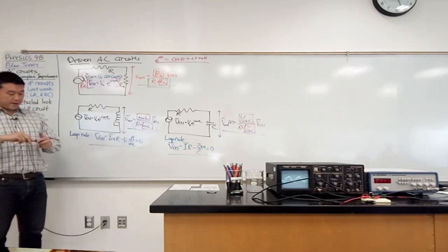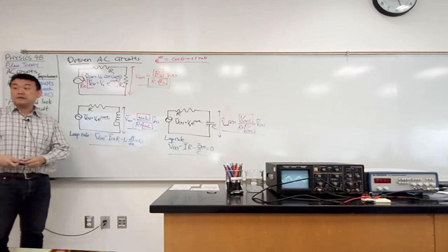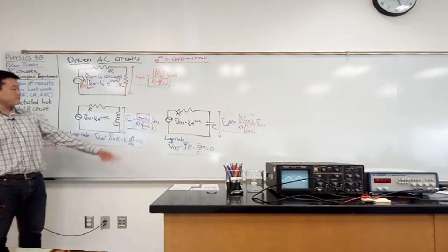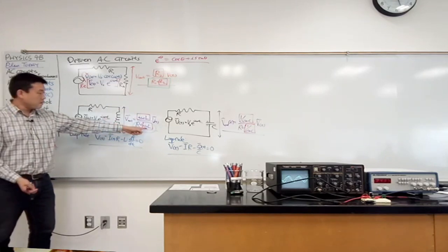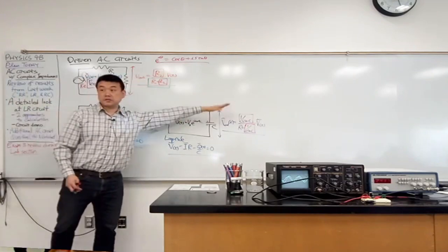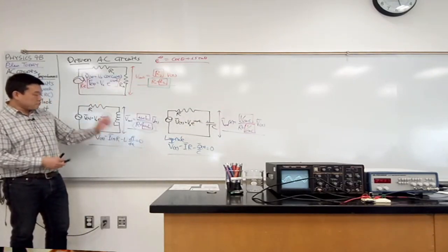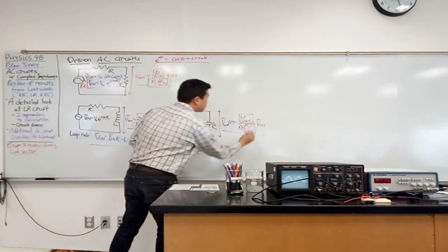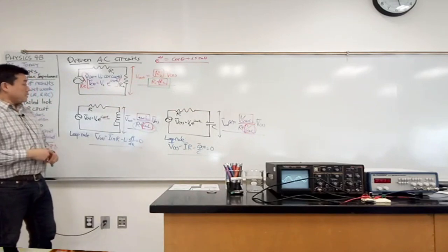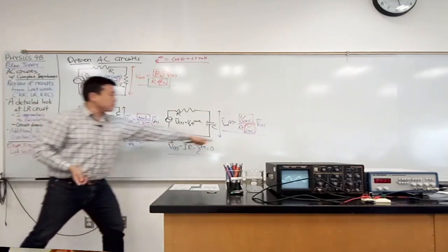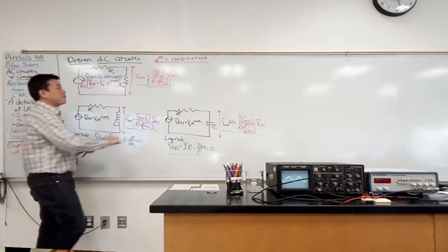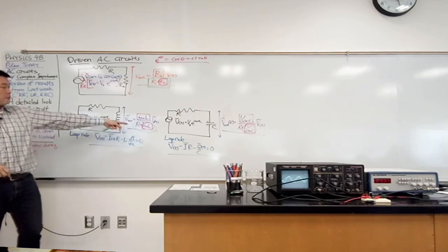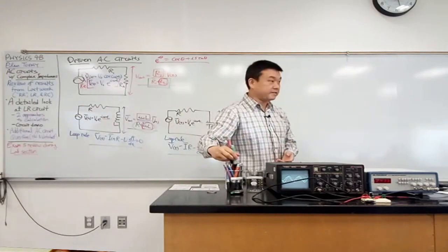I ideally should have had time to introduce complex impedance, but we sort of abruptly left. We got as far as this, and then you guys at least got to see the similarity between the expressions, and you got to see at least this far of the expression, iωL and 1/iωC. That actually should be in your notes. And that occurs in a place in an equation where it can be compared with R2. So the intuition that we are trying to build up there is that this is a quantity that behaves like resistance.